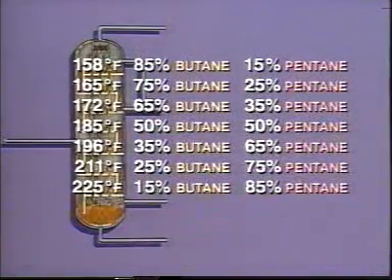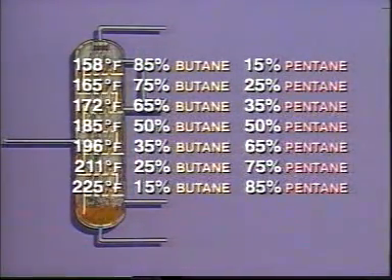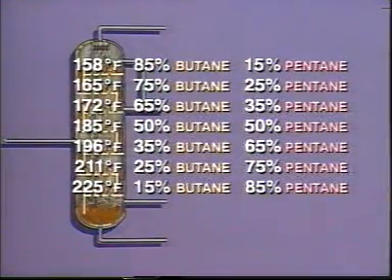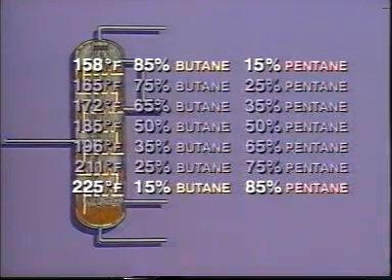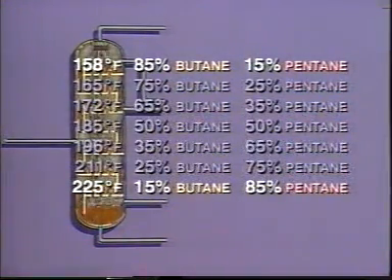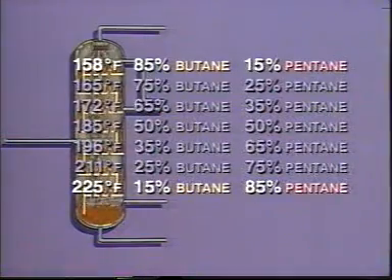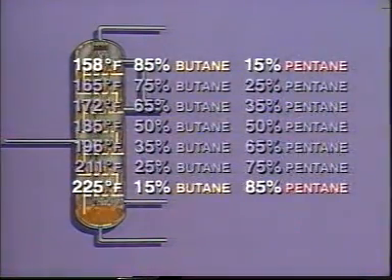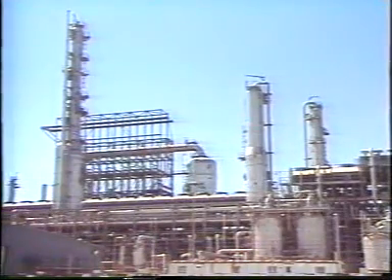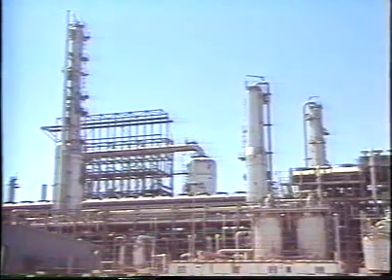If we add a sufficient number of trays to our distillation column and keep each tray operating at a slightly different temperature, we can isolate what is essentially pure butane at the top of the column and pure pentane at the tower bottom. We usually consider a distillation column as being divided into two main sections.